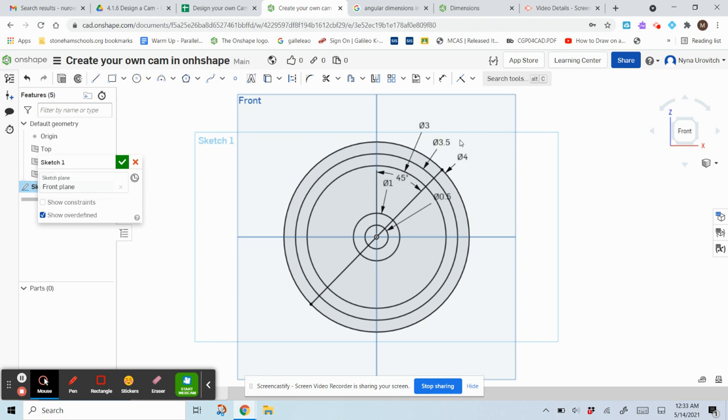Okay. We're going to do another diagonal line. Again, you start on the outside, you go through the center, but you always have to do the coincident constraint. Okay, so I have the line. Great. And now we're going to dimension it. We have the 45-degree position between one side and an axis. Here it says 37. I'm going to switch it to 45.